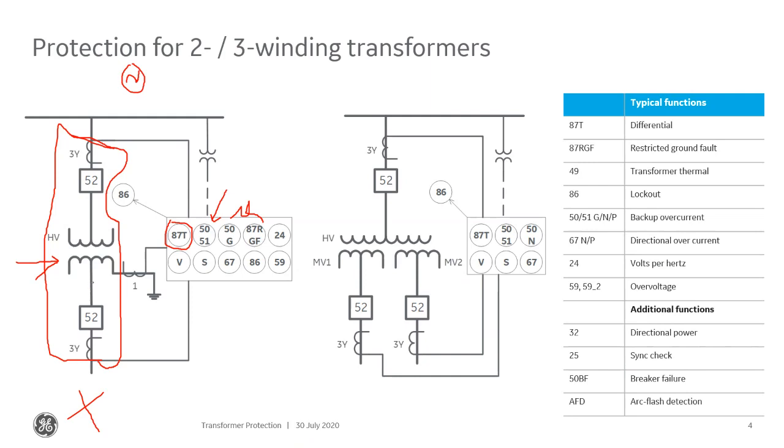Likewise, I mentioned earlier that we may not operate for all of the ground faults with the differential. So one of the things that we can also do is create a ground differential between this CT here and this CT here, so that forms a ground differential zone of protection with the restricted ground fault element. Basically what the restricted ground fault element is doing is comparing the 3I0 from the phase CTs down here to the measured ground current. And that's what that element is doing.